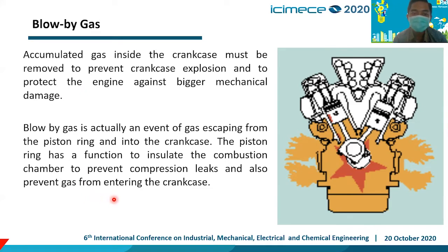The piston ring has a function to insulate the combustion chamber, to prevent compression leaks, and also to prevent gas from entering the crankcase. As we can see in the image here, this is the compression in the combustion chamber, and the blow-by gas will go through the piston ring into the crankcase and makes the crankcase pressure positive.